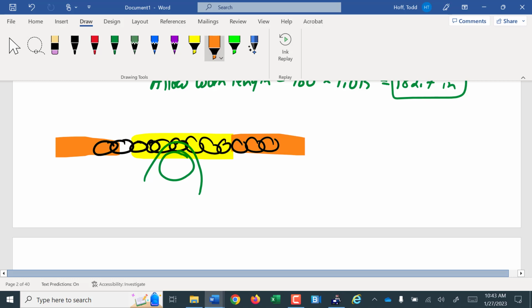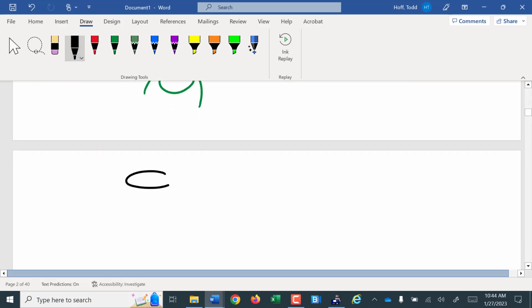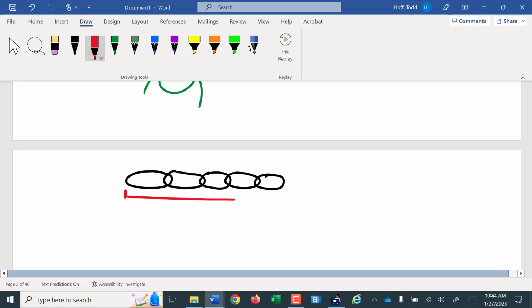So you'd want to be taking that chain and you want to measure section by section. Usually you don't do a single link, but you usually do 3 or 4 links at a time. Say new, the length from here to here. If you fold the chain and stretch it out as far as it'll go with those 5 links, find what the new length was, and then now after it is worn, what that length is.